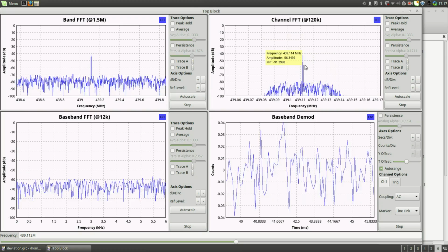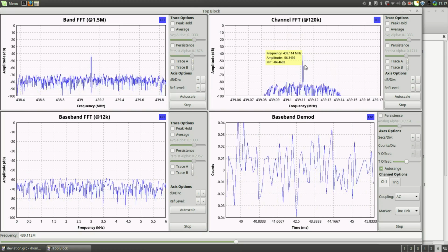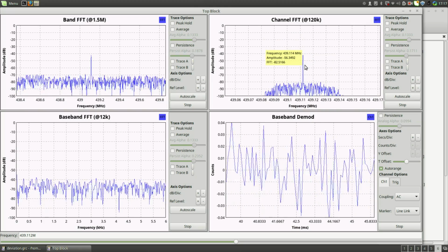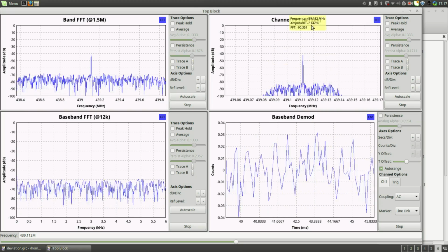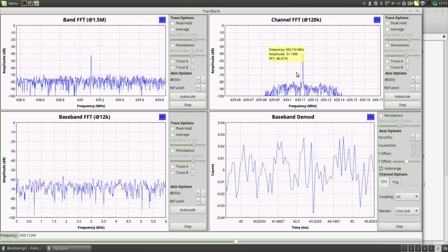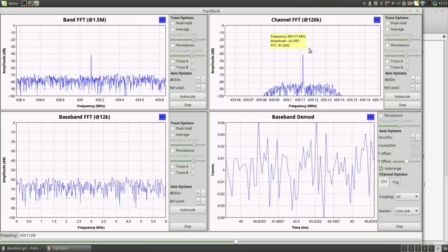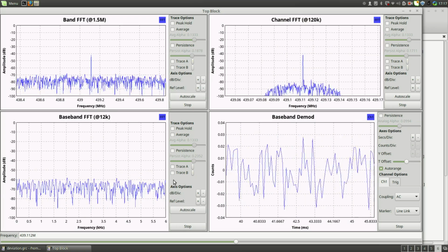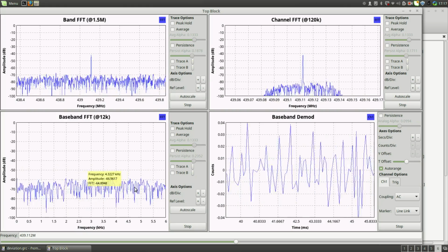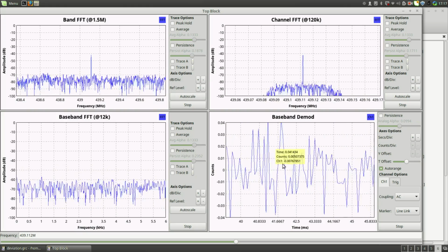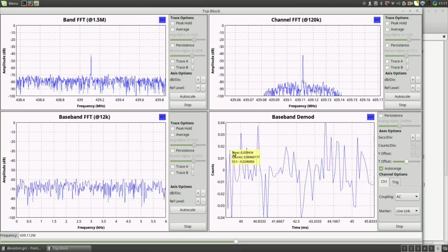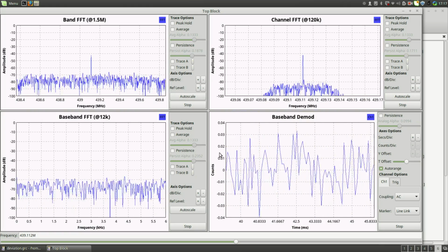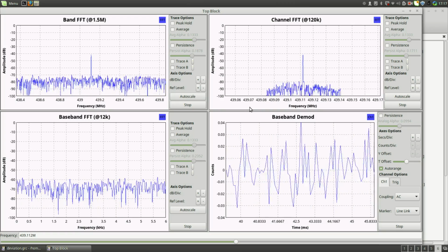center it very well. And now the SDR hardware is not tuned to exactly 439.15 megahertz anymore, but this is just compensating for the error of that clock. So that's nice. And here I have a flat noise floor because I don't have any modulation at all. So basically this should be full quieting on my receiver here. And equally here, that looks like a mess, but it's just auto-scaling to a scale that is not really significant.